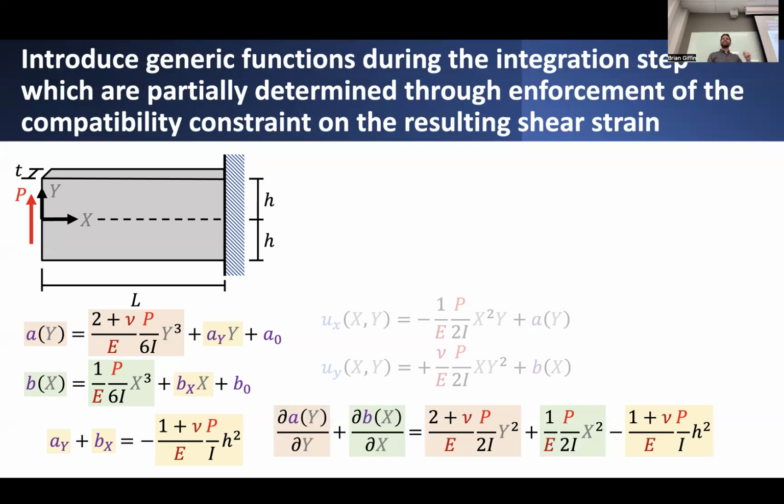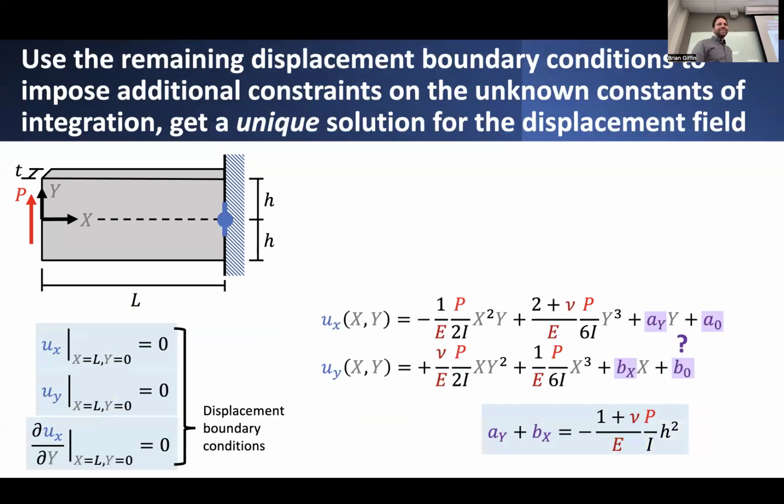We didn't need the displacement boundary conditions when we were solving for the stresses because we were totally complete and specific about what the distribution of stress looked like on the boundary of this domain. Now, however, if we're trying to find displacements, we have to dig up those old displacement boundary conditions, these constraints that I was a little bit funny about when I defined them.